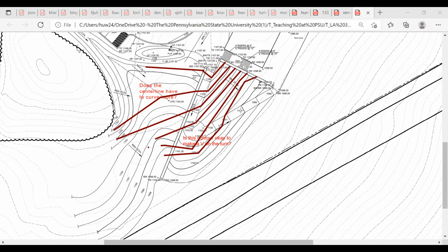Does that make sense? So you don't need a wall. We could just aim for such type of connection. Something needs to happen. It needs to turn a little bit just to wrap around the wall, wrap around the ramp a little. But you can see that's quite doable because you have enough length. I just wouldn't design for the side slope to be very steep. For that reason, I probably would change this to just like that.